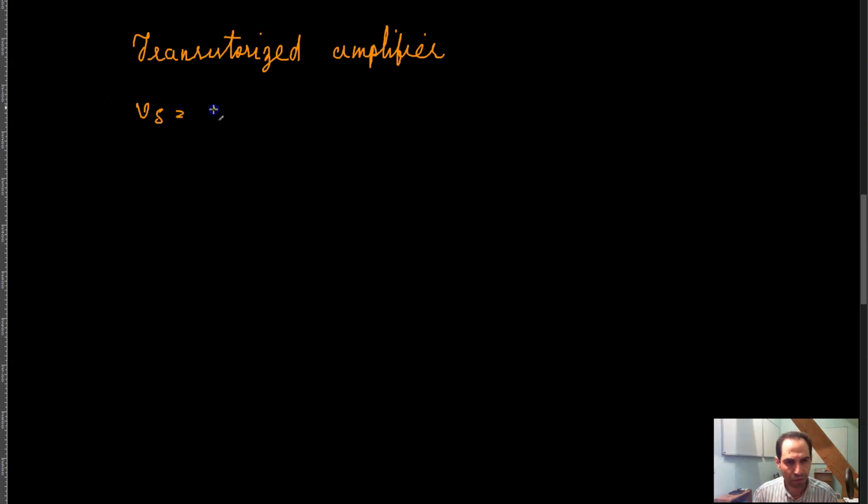So V of S is equal to 9.0 volts. Now the minus terminal is at common chassis ground, and at some point you need to get plus 2.5 volts. Give an example of a pair of resistors that can be connected in series such that plus 2.5 volts will be provided at some point. So in this circuit, at some point you need to get a voltage of plus 2.5 volts, right?